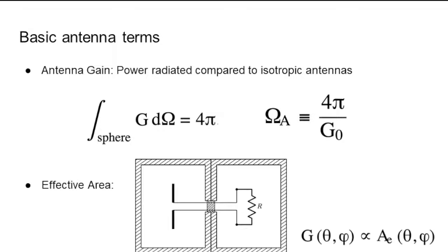When you are observing with your telescope, you will measure temperatures of 1000 Kelvin, 10,000 Kelvin, even a million Kelvin, depending on what you are looking at. RFI, the interference, can go up to billions of Kelvin. But it's not that thermally they are at those temperatures. Impossible. So what you are doing is some kind of a radiance approximation. You are asking, okay, I receive a power which is so much in specific intensity units. How much should I heat a resistor?